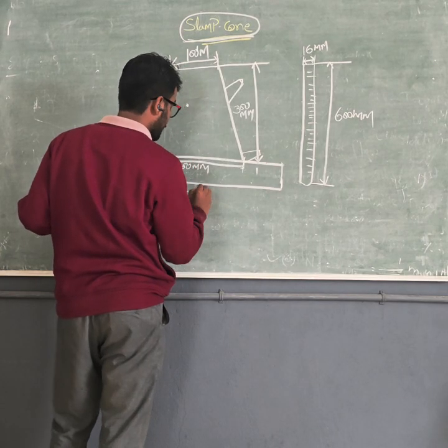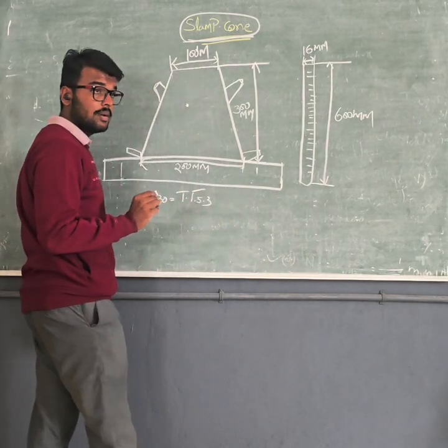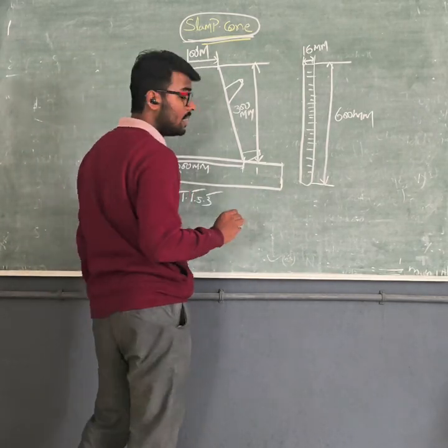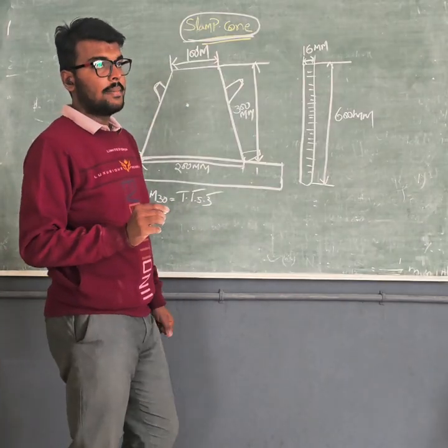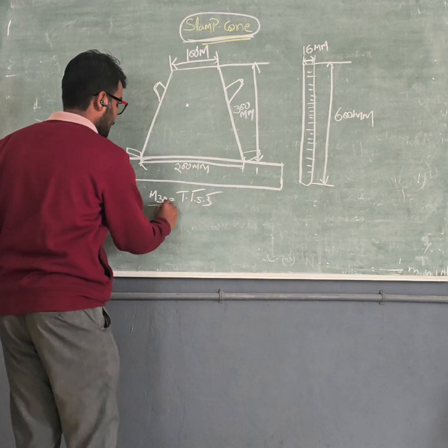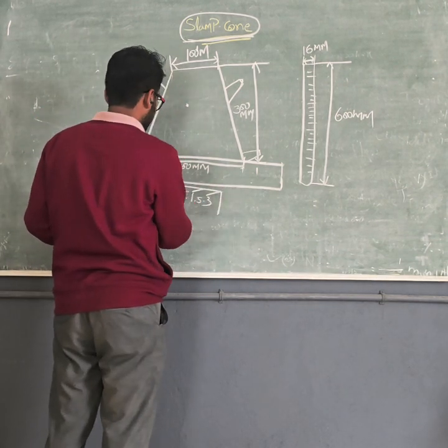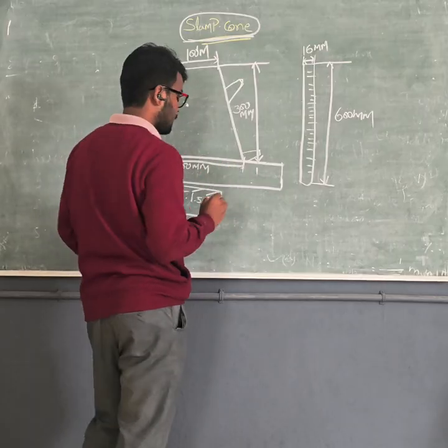That means if we add 1 kg of cement, then we add 1.5 kg of sand and 3 kg of coarse aggregate, by which we mix the concrete for M30 grade. For this process, we need to use the weighing machine in this test.